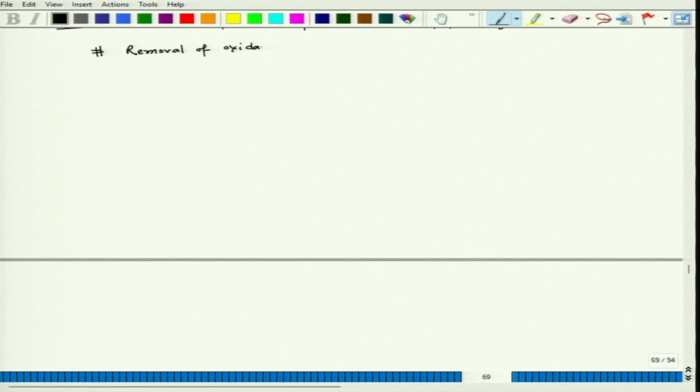Or oxidant. And what are the strong oxidants? Let us say Fe3 plus. So, if we consider HCl, an iron container is there. So, this we have iron container, then HCl, if it is impure, when it is impure, that time we can have Fe3 plus, a very small percentage of Fe3 plus. What could be the influence? We can explain this with the help of mixed potential theory.